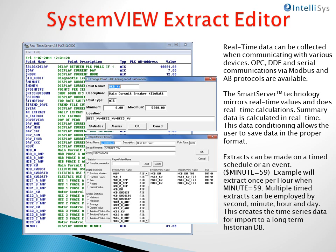Extracts are made on a timed schedule or based on an event. Typically, an hourly event might be minute equals 59. In that example, at the end of every hour, when the minute equals 59, the extract would be fired and the data would be collected. Multiple timed extracts can be employed by second, minute, hour, day. This creates time series data for import to the long-term historical database.